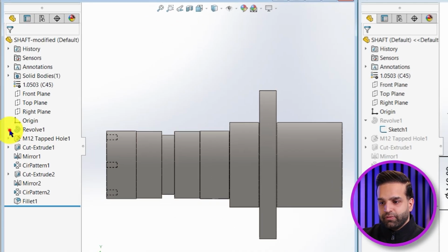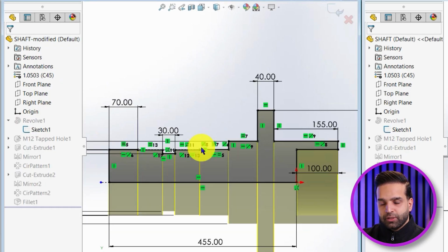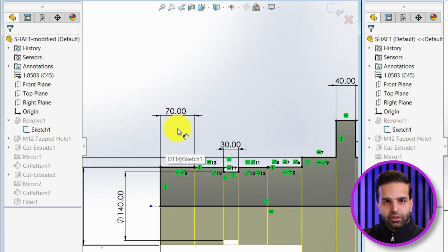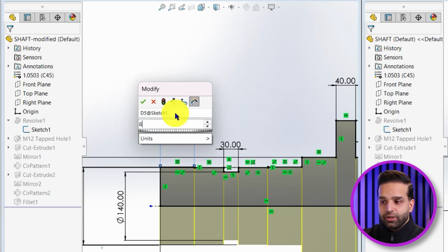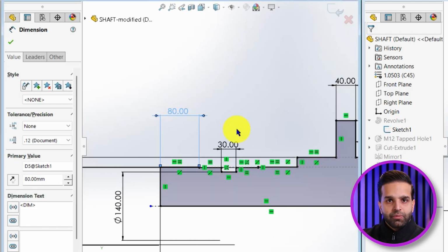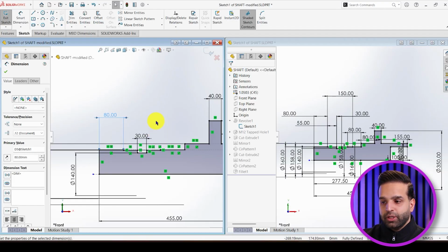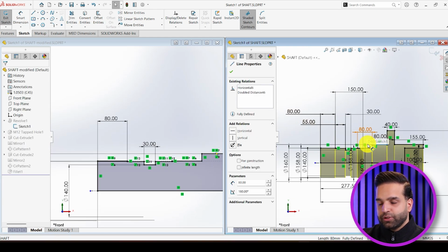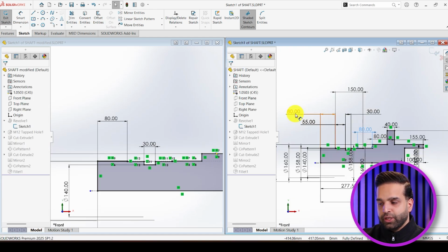Now this time I define the sketch using the relations as my first choice. If I want to do the same modification, I only need to edit the feature with dimension, and the relations will take care of the rest. Just be aware of the dimensions, that they are equal, not that they have similar dimensions. For example, I know that this one is equal to this one, but maybe it is not equal to this one necessarily. So you might want to change these 2 ones, but not this one.